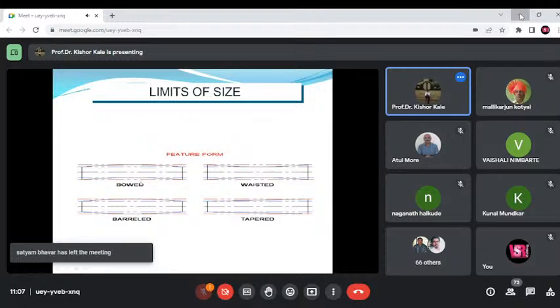So actually how does it work? In the feature control frame, the geometrical symbol is shown over here. The tolerance information is in the second part. The datum references are in the last three parts. So datum is the reference, and the references may be 1, 2, or 3, so the maximum would be 3. In some cases we may use only one reference, sometimes it requires 2, and sometimes it requires 3. That depends upon which dimensions you are giving and what we want to control.